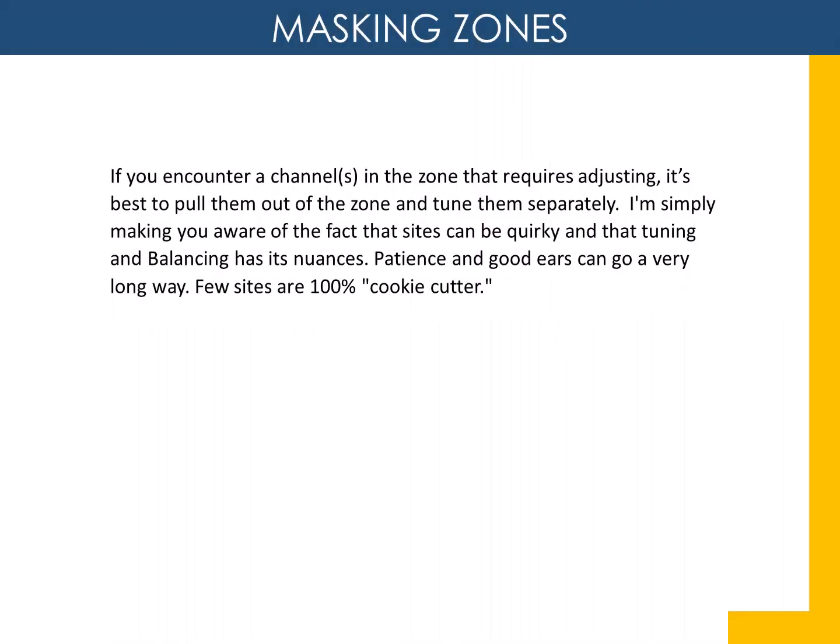Should you encounter a channel or channels in the zone that requires adjusting, it's best to pull them out of the zone and tune them individually. I'm simply making you aware of the fact that sites can be quirky and that tuning and balancing does have its nuances. Patience and good ears can and will go a very long way. Few sites are 100% cookie cutter.